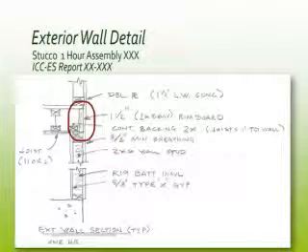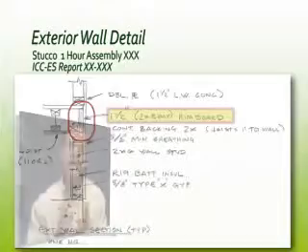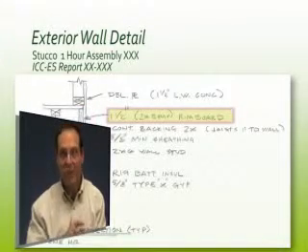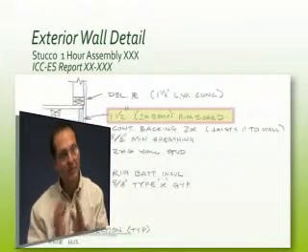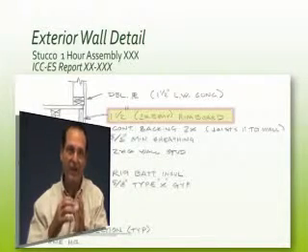But that cavity in between is where you can get in some real difficulty from a specification standpoint. The simple way to do this that this architect took was simply to spec a 2x equivalent, which is dimension lumber essentially. In the code it is listed as fire blocking. There's a difference between fire blocking and draft stopping. We're talking about fire blocking here, as long as it's something that physically blocks the passage of fire.